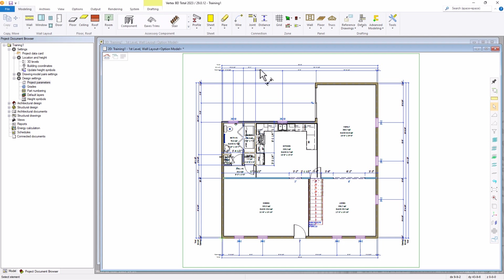In the second training video titled Walls, we covered wall frame tools. The wall frame tools are rules assigned to a wall that instruct Vertex which framing materials to assign to a wall, framing details, on-center stud spacing, framing around openings, and various other wall framing settings. Wall frame tools is part of the wall framing layer within a wall type.